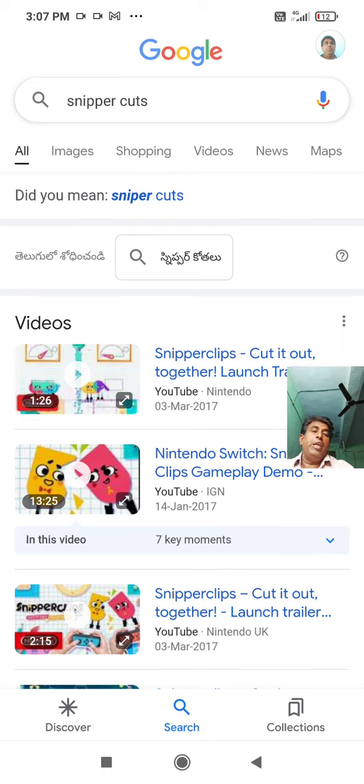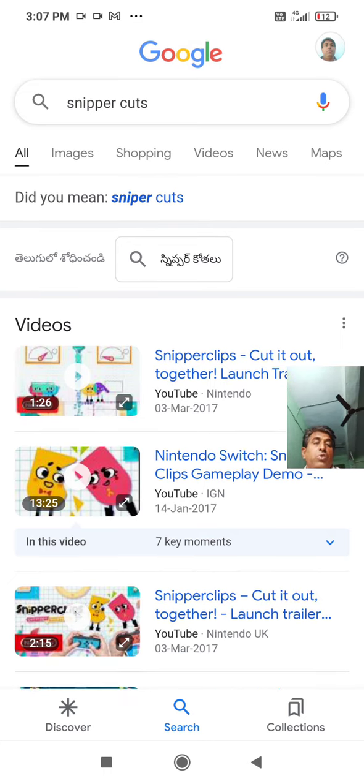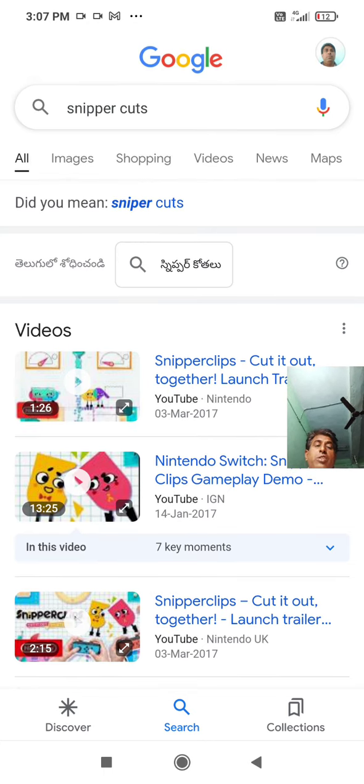And peel strength or bond strength we have studied in fusing. And in that we have seen strike through defect and strike back defect. Strike through is a defect where resin comes out of the surface of the outer fabric. Strike back is where the resin is forced to the back of the interlining.